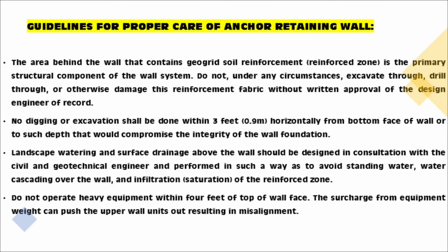So here are some of the guidelines for proper care of anchor retaining walls. The area behind the wall that contains geogrid soil reinforcement, or reinforced zone, is the primary structural component of the wall system. Do not, under any circumstances, excavate through, drill through, or otherwise damage this reinforcement fabric without written approval of the design engineer of record. No digging or excavation shall be done within 3 feet or 0.9 meter horizontally from the bottom face of the wall or to such depth that would compromise the integrity of the wall foundation.